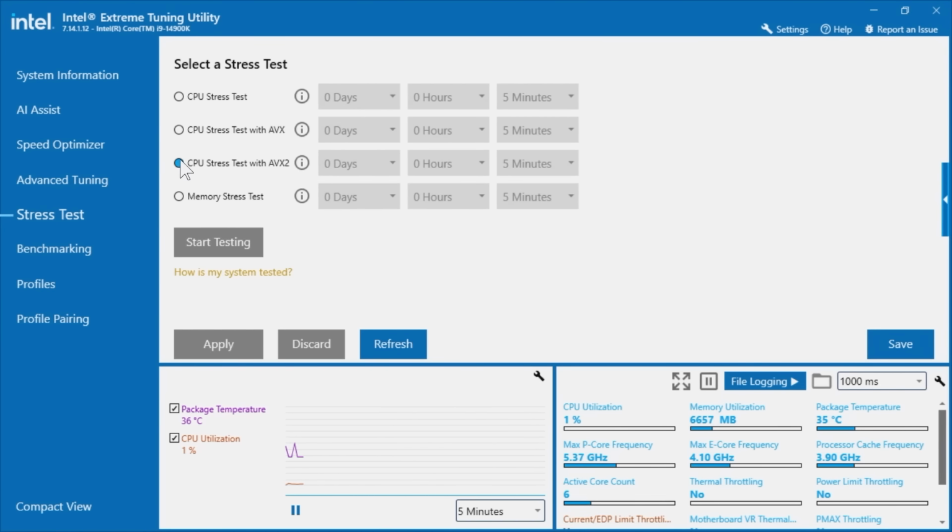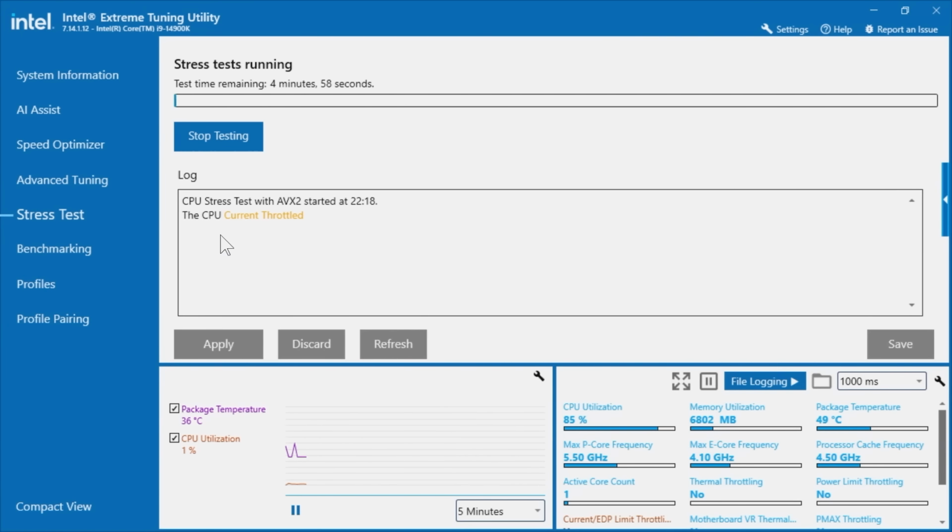And you can see the example where it places the CPU processor under extreme stress testing. So once it's running, you can see that we're hitting that current throttle and the power throttle due to the implementation of the ICC Max and also the PL1 and PL2 settings that we physically set in the BIOS. So that's essentially what it's telling you here. If you were to run the standard Asus overclock profile, there would be no restrictions on there, and the test would potentially fail, or it would firmware throttle during the course of the test.